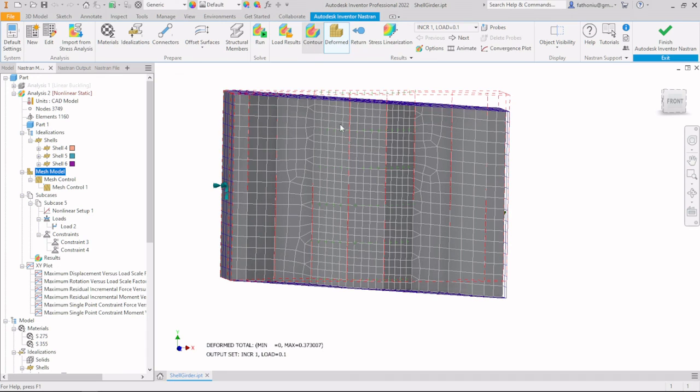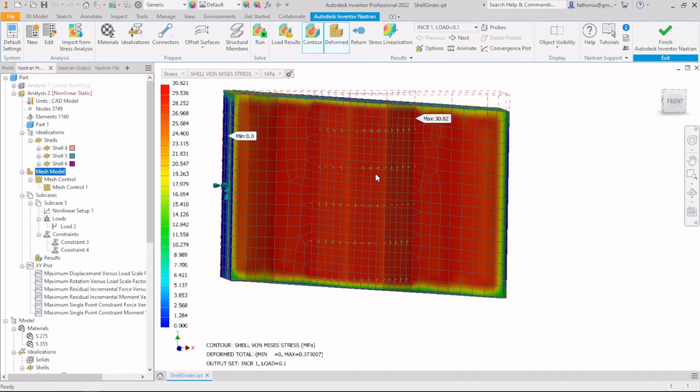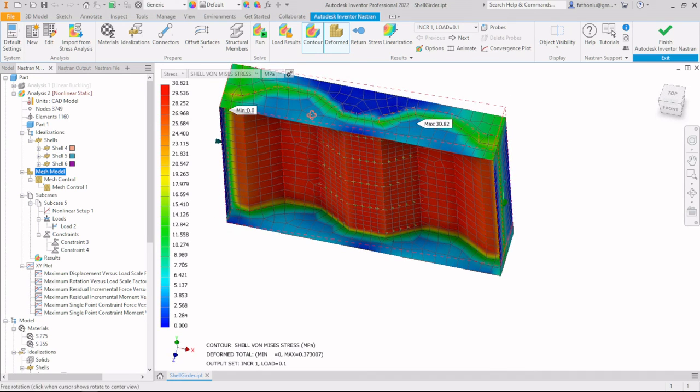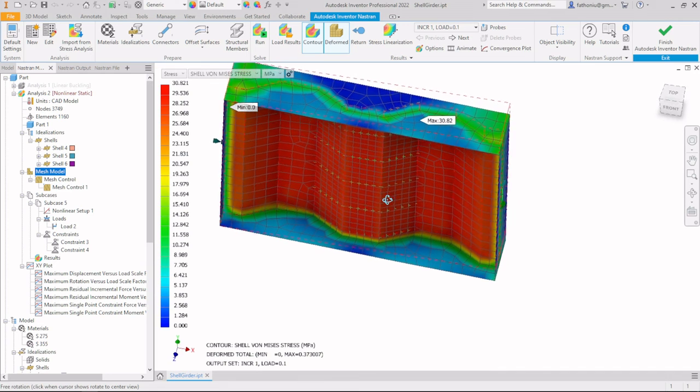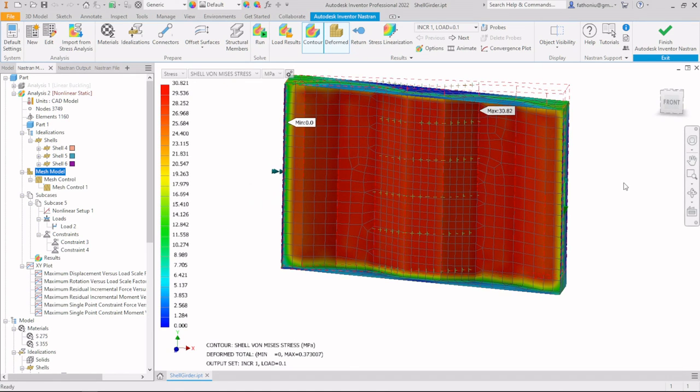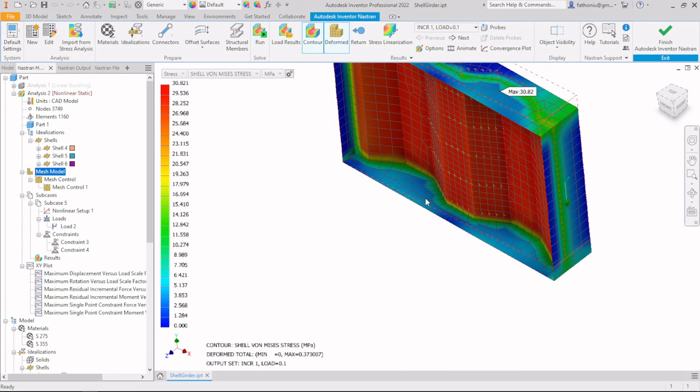Anyway, the contour here. The linear buckling gives you an exaggerated deformation. Here we can see that this 60 degree corrugated shape will not really give a stiffening effect on the web. So as suggested in the code, EN Eurocode 3.15, it's supposed to be 30 degree and the alpha.